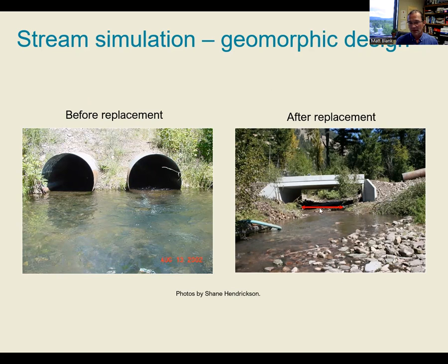It's actually a bridge in this case, but here's the active width, and there's the bank full width within here. You'll see those nice margins along the edge, which provide almost a riparian corridor through the structure and certainly provide not only fish passage, but also small mammal passage and semi-aquatic passage as well.